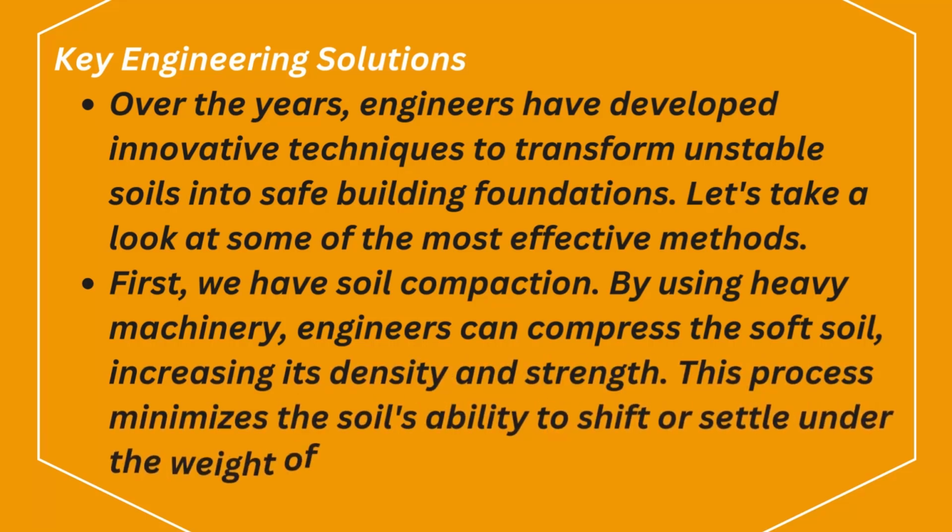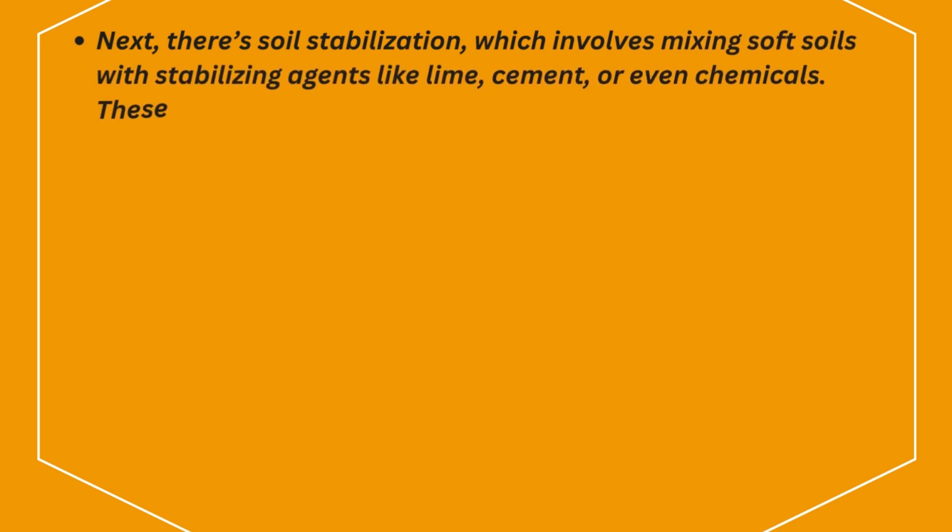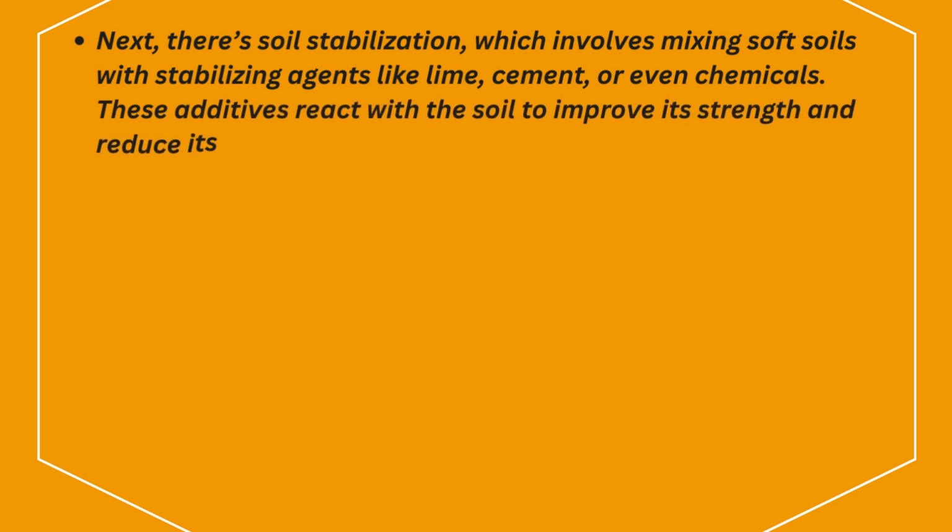This process minimizes the soil's ability to shift or settle under the weight of a structure. Next, there's soil stabilization, which involves mixing soft soils with stabilizing agents like lime, cement, or even chemicals. These additives react with the soil to improve its strength and reduce its moisture content, making it more suitable for